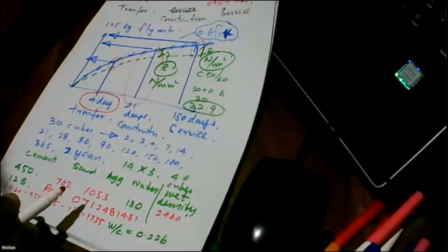If we cure the concrete properly in the first few days and generate sufficient calcium hydroxide as the byproduct, concrete is definitely going to gain strength over a longer period, because fly ash is going to start a secondary reaction with this calcium hydroxide and generate more and more gel. With more and more concrete gel, you will get higher strength. And finally you can achieve your target.